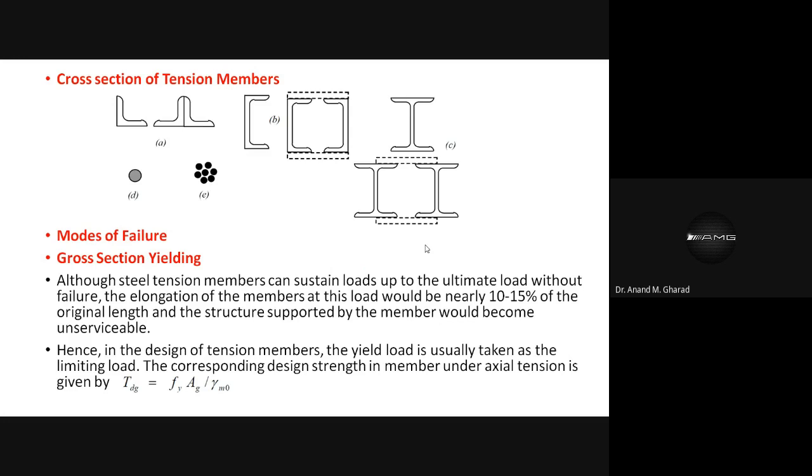Okay, so just for time being, try to understand that whenever we are designing any bolted connection, we should take care of the end distance, edge distance, then the pitch distance. Pitch is nothing but the center to center distance between the bolt holes, right? So all these things should be taken care of. Now there is some methodology, some background, depending on which the minimum values of edge distance and end distance are given. If you remember the pitch distance criterion in your IS 800 2007, it says that it should be minimum 2.5 times the diameter of the hole.